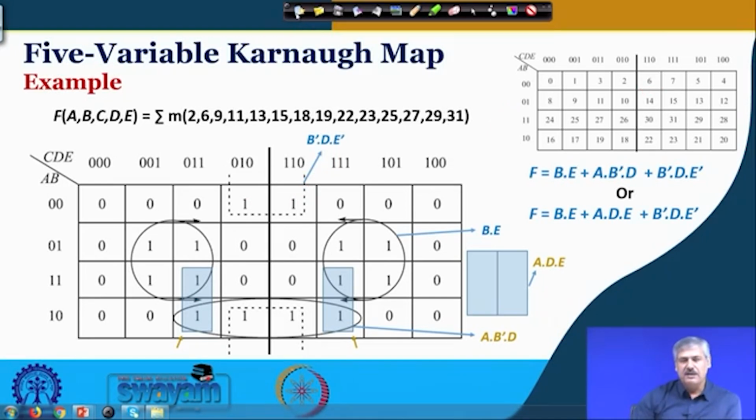Okay. Now, after that we need to do the grouping, and in doing the grouping we need to consider logical adjacency, both in the neighborhood region, which is clearly visible, as well as the one that comes through the reflection, the one that we just discussed. The one that we can see is a group of 4 over here. Now, about this vertical axis, you can see they are just reflections of one another, so they are logically adjacent.